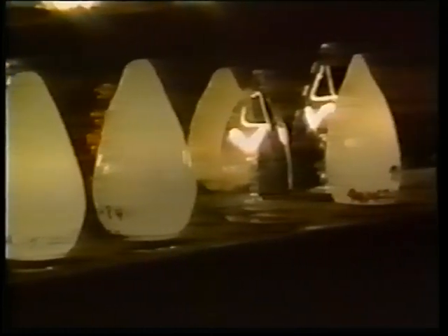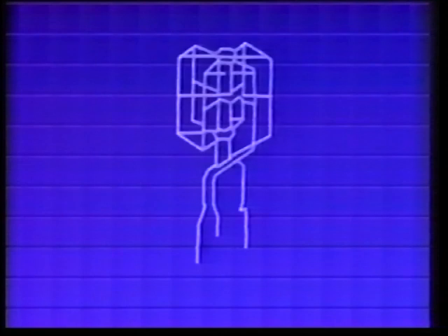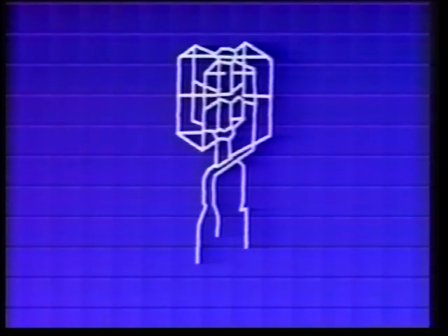We've already discussed how the shape of a filament affects the efficiency of the lamp. Well, both the filament and its support can affect the lamp's durability as well. The supports for the coil are dictated by the end use for the lamp. The more support used, the more it touches the coil. That reduces efficiency because it cools the areas that it touches. So in creating a support, we try to combine durability with the highest possible efficiency.